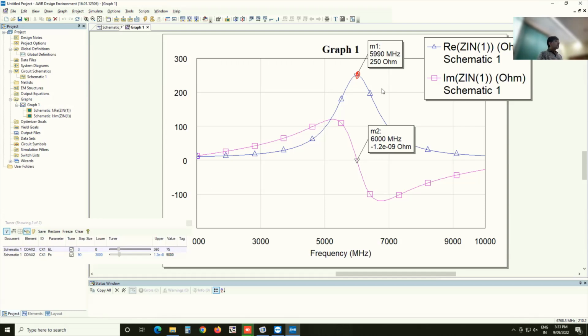That by definition will have a certain fractional bandwidth. What do I mean by fractional bandwidth? It depends on the center frequency at which you are operating. So often you will hear or see things like 10% bandwidth. It means that it is considered matched within 10% of the ideal frequency, which in this case is 6 gigahertz. But as you move that frequency along, the absolute bandwidth will change because it's always related to the frequency for which it is designed.